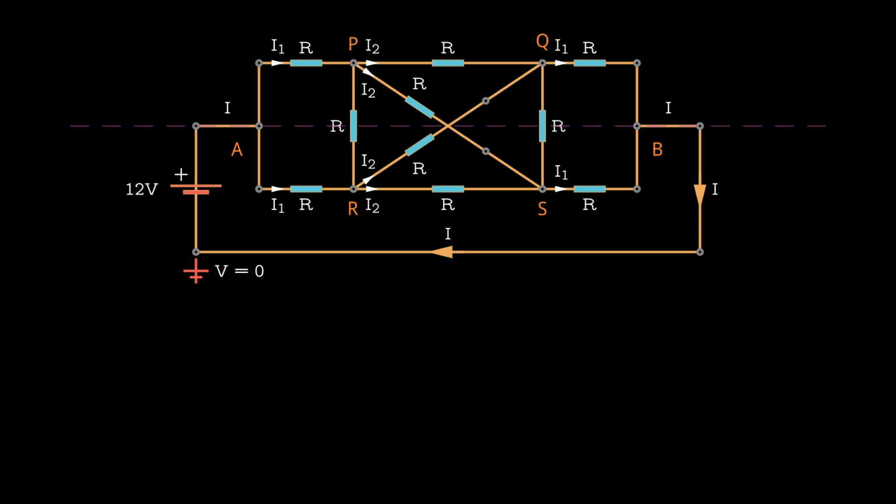Now, let's trace the circuit, starting from the positive end of the source, and move along until we encounter a junction or resistor. We first reach a junction. At this point, we need to verify if the branches diverging from this junction are symmetrical with respect to the axis. We should only select the branches that exhibit symmetry along the central axis. Once the symmetrical branches are identified, we can trace along them simultaneously until we encounter another junction or resistor.